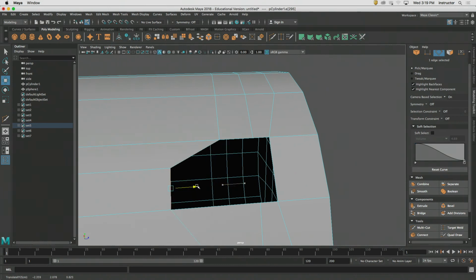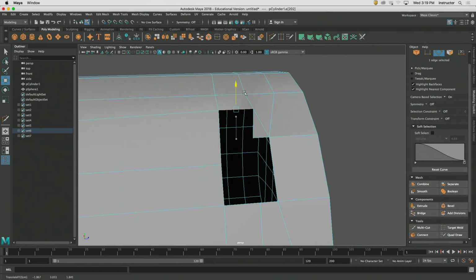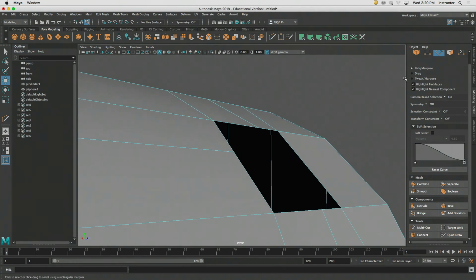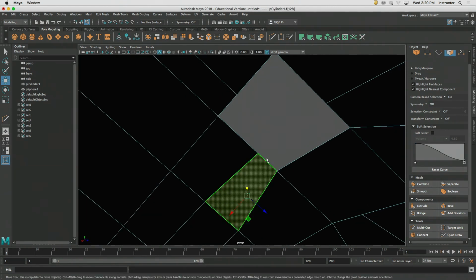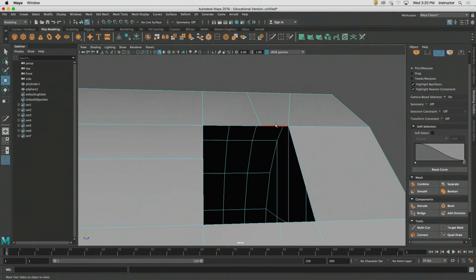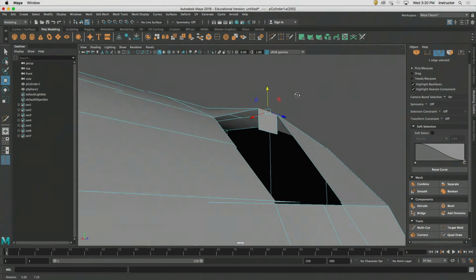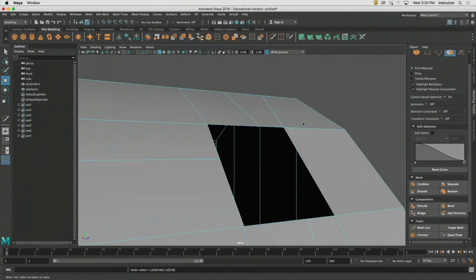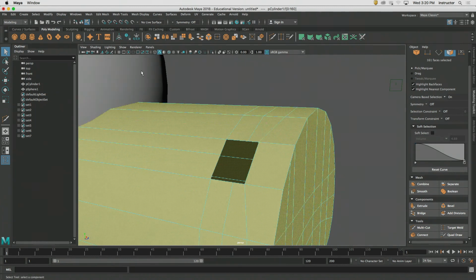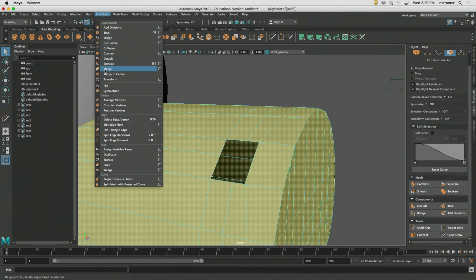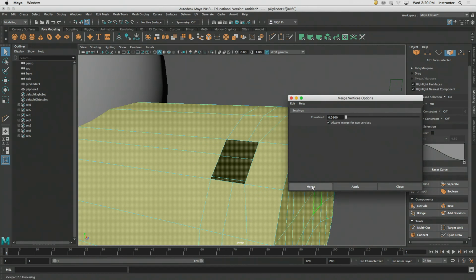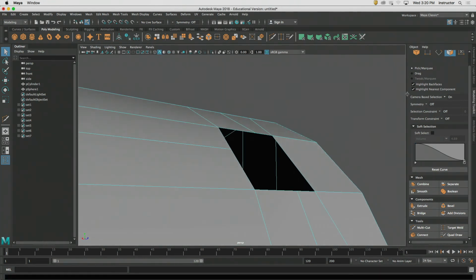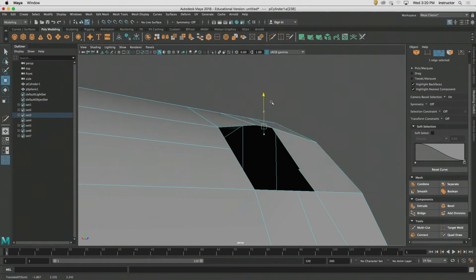See, that fix it? That's looking pretty good. There's also a hidden surface right in there. Let's see if we can figure it out. In theory, that would work. Merge would, let's just run that test real fast. Select all our geometry, run merge. Let's see if that solved it. Yep, that did it. That did it.